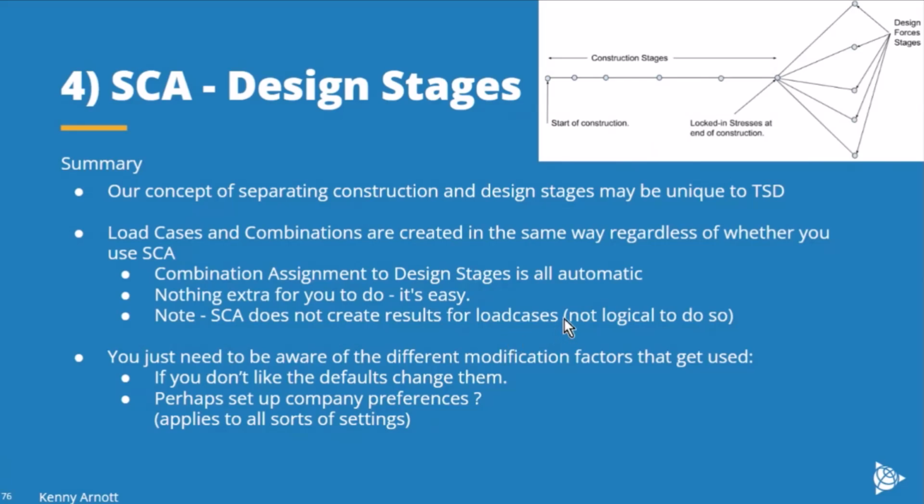And just an extra note here is that stage construction analysis does not create results for load cases in isolation. Thinking of a wind load case, for example, a wind load can never exist in complete isolation. You will always have some level of loading built up, and then wind happens. So that's effectively what happens here. If we were to try to analyze for the wind case only at this point, you would have to reduce the load that had accumulated by the end of construction. So it's basically not a logical thing to do.